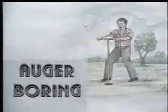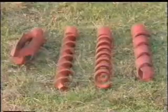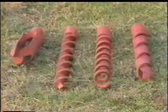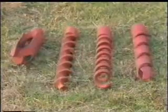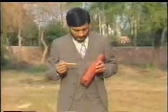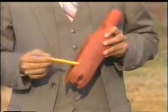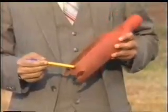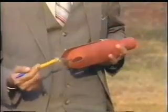Auger boring is the simplest method of sampling. Different types of augers are used for different soil types and depths. A hand-operated post-hole auger having sharp blades at the bottom can be used for exploration up to 6 to 7 meters.